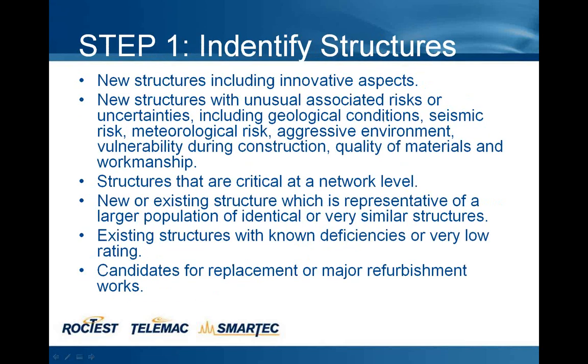First step, identify structures needing or benefiting from structural health monitoring. Of course, it would be nice for me to say that all structures need structural health monitoring, but experience has shown that some of them can have more benefit from structural health monitoring. These are in particular new structures that include some innovative aspects in terms of material, construction procedure, shape, location, etc. Also new structures with unusual associated risks or uncertainties.